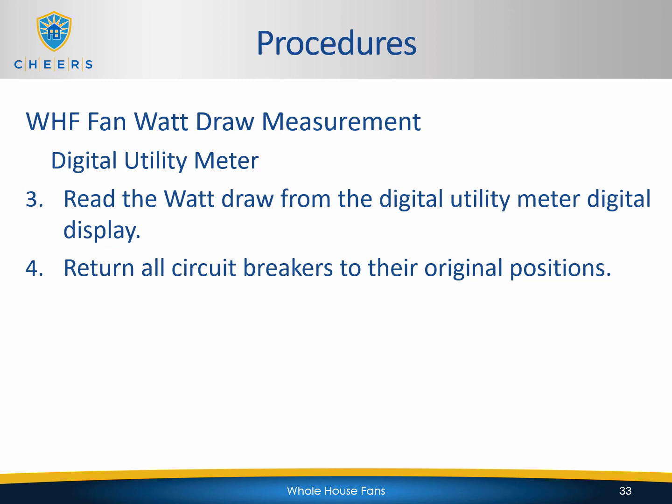Now, as I mentioned a little bit earlier, if it's not reading the right watts or the watts just aren't coming around, there is the ability to treat it as if it was an analog meter. It'll have the bars at the bottom that scroll across the screen, and that represents the black stripe on the wheel turning around. So you can just do the same thing: wait until those black stripes come across, and then start your stopwatch, count the number of revolutions, stop your stopwatch, perform the calculation, and you will get your watt reading that way.